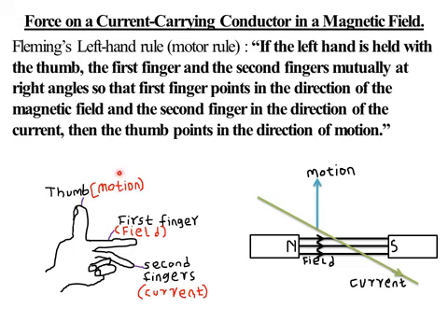And the other thing to remember is that it must strictly be the left hand. It must be the left hand, because if you apply the same with the right hand, you'll actually obtain opposite results. So you take your hand, then the first finger, you align it towards the direction of the field. The field, we've said, moves from the north pole towards the south pole.